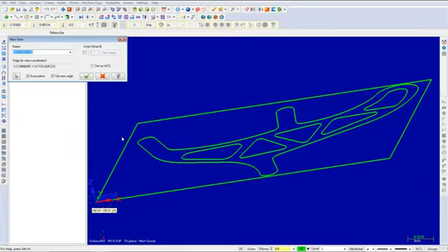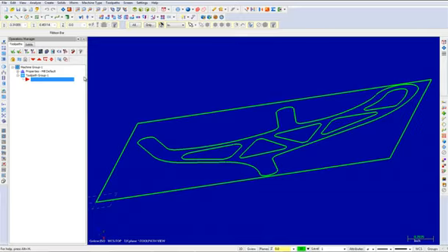In the new view, change the name to Toolpath View and leave the other parameters. You can now select the OK button once complete. You should note that the grid shows you the new plane.